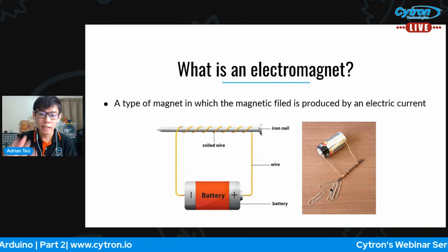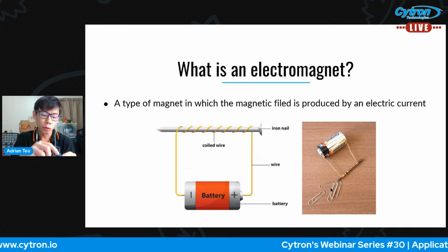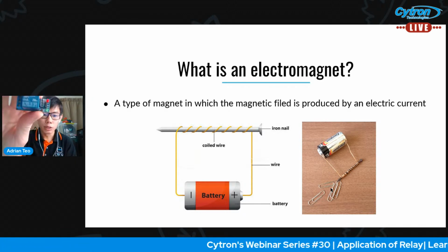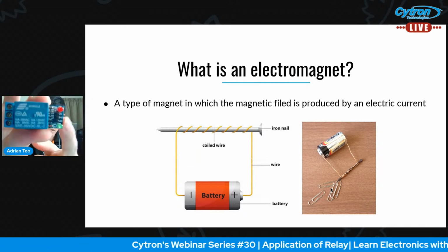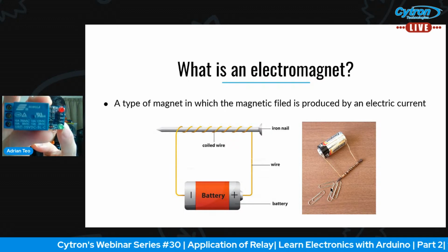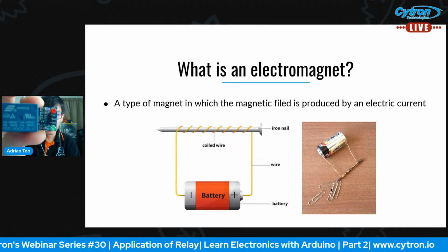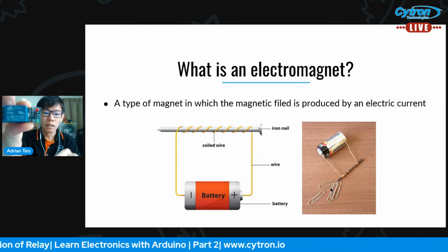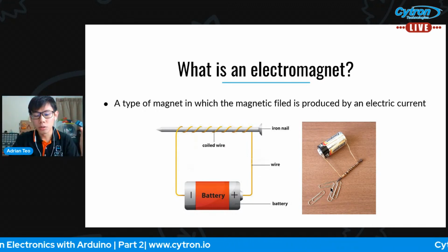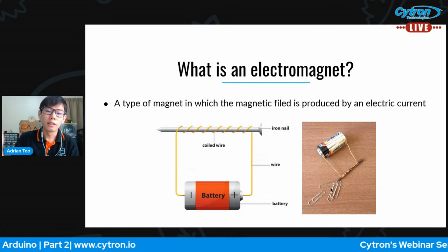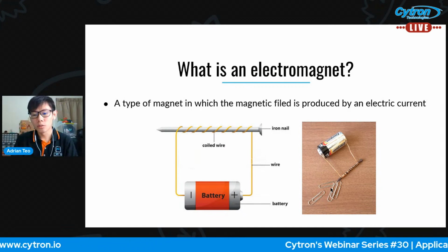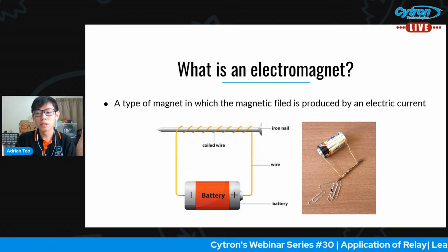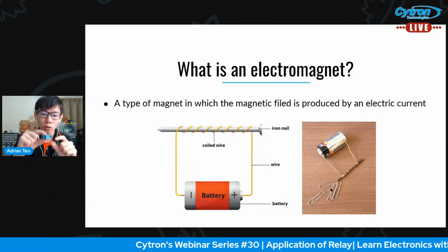And to program a high signal means you apply 5 volt to the input. Okay, that's ground and voltage, VCC, ground, voltage. So if you apply some voltage, a signal to IN, it's going to disconnect the switch. Okay, apply signal, it will disconnect the switch. You don't apply signal, it will stay connected for your switch.